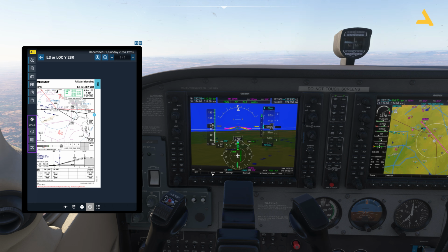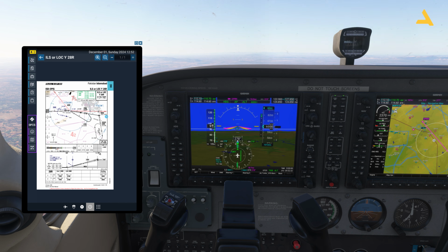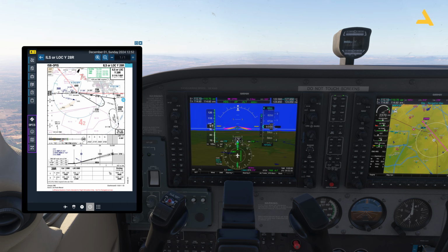You can do another thing. Go to this PFD option, bearing, and let's bring the ILS. So ILS is coming, and plus I can also press DME. It's 19.3 nautical miles away. So roughly here at this distance, 6 nautical miles, you should be at 3,700. So let's even start the descent.